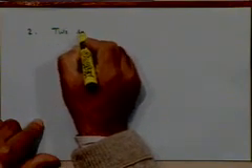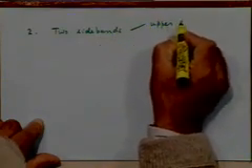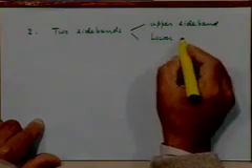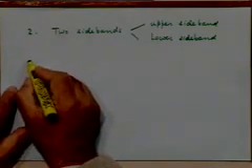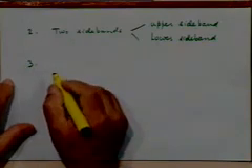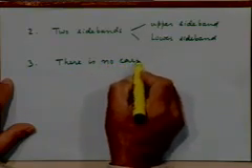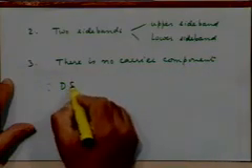So the other properties that we have just learned are that the waveform has two sidebands, an upper sideband and a lower sideband, and that there is no carrier component. And hence the name double sideband with suppressed carrier.